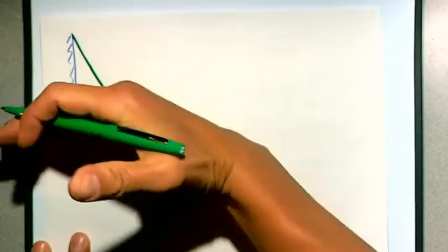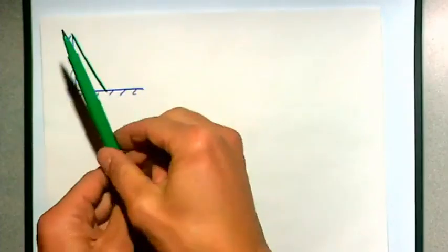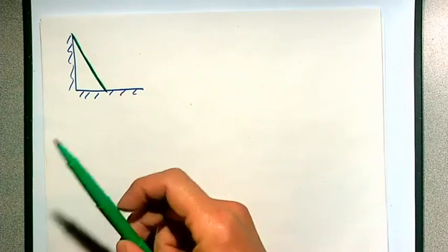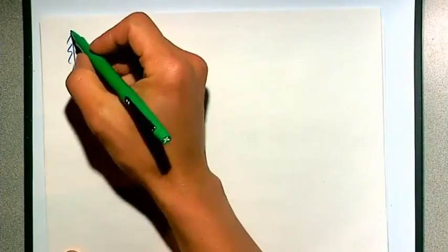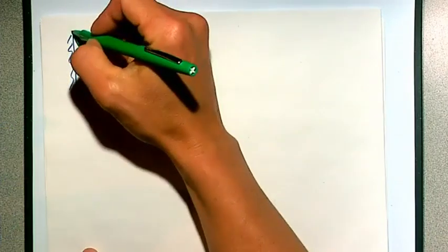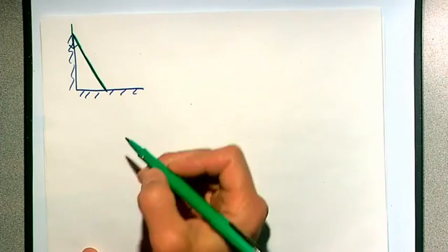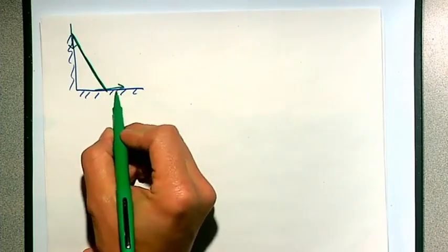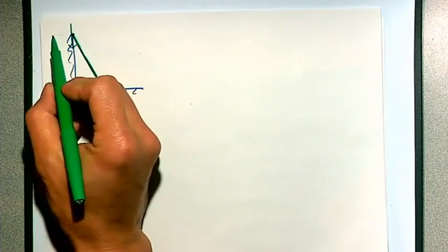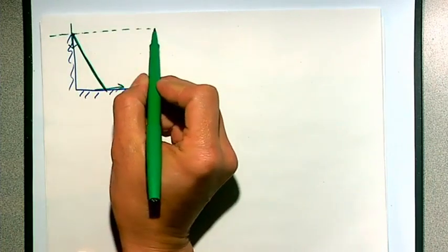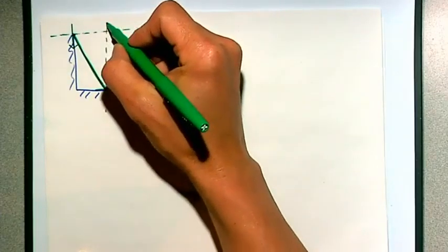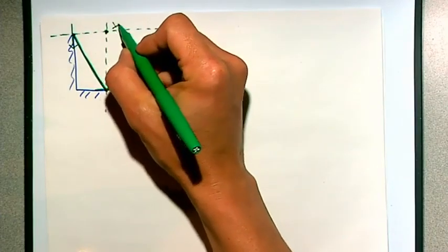So as this thing is falling, my ladder comes like this, whew. It's doing some rotation, some translation. But if I can figure out the instantaneous center, assuming it stays touching this wall and touching the ground, my velocity at the top, my velocity at the bottom, and then to find our instantaneous center, those contact points go perpendicular to our velocities. Okay, that's my IC.